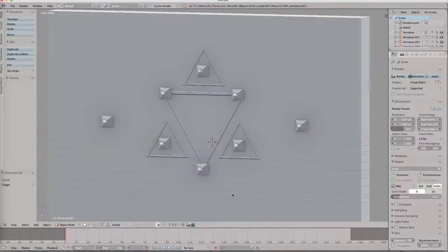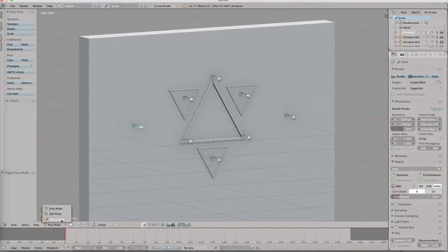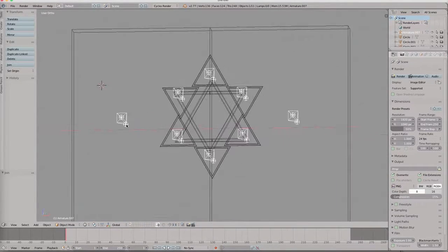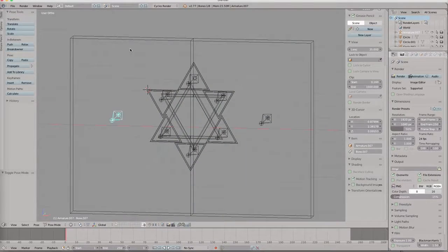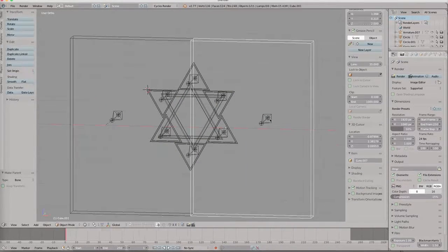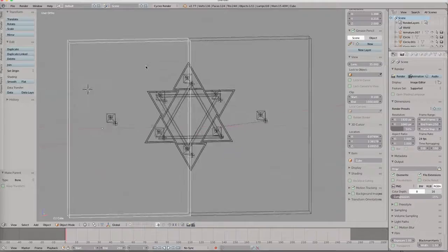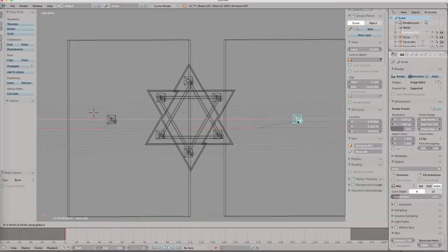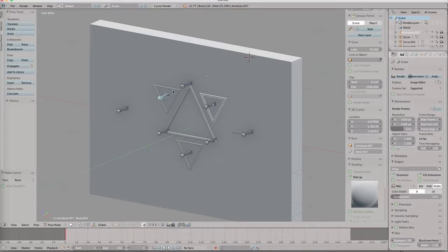In your mesh tools, there's a join option, or I believe you can hit Control J after selecting them all, and you'll want them all to be one. If you have them as separate, individual bones, then when you go into pose mode, they'll kind of be their own little island, and I've found Unreal will not work with that. It likes something that's similar to a skeletal mesh, where it has somewhat of a root.